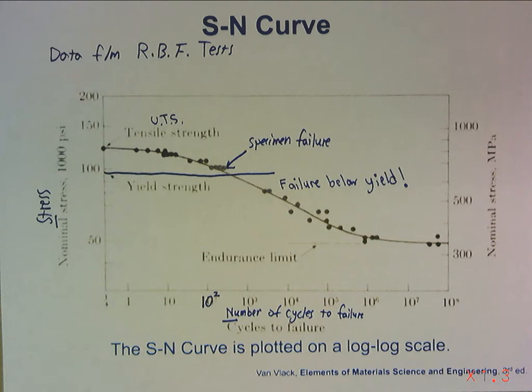So once you throw in a stress concentration at that point that we are starting a fatigue failure, then is that point of stress concentration really below the yield stress? Probably not. It's difficult for us to go in and identify exactly what every single scratch that may ever happen on a part is going to do to the stress concentration and the stress before it happens.